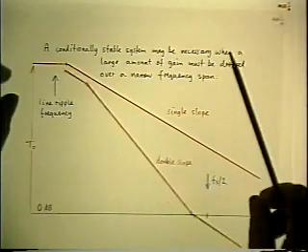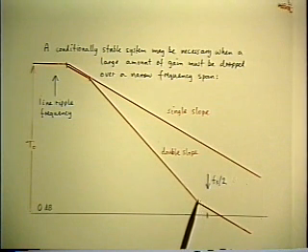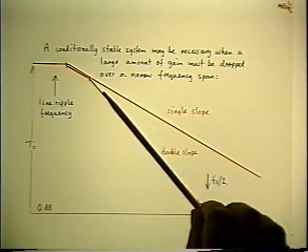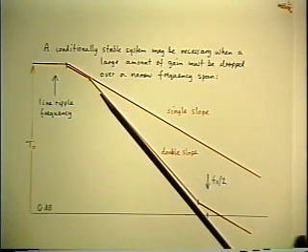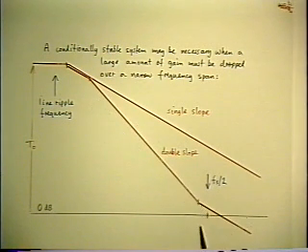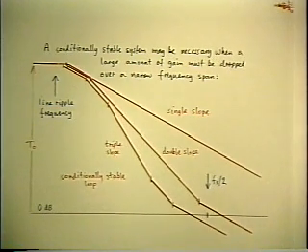So you try 2 poles. And if you put a second pole in, you also have to put a 0 in, because you have to prevent the phase angle from getting to 180 before crossover. And if you didn't put the 0 there, you're already at 180 before you get to crossover, and you have no phase margin. So you have to put a 0 in. And suppose you still don't make the window. Then you have to go to 3 poles and 2 zeros. Now you make the window.